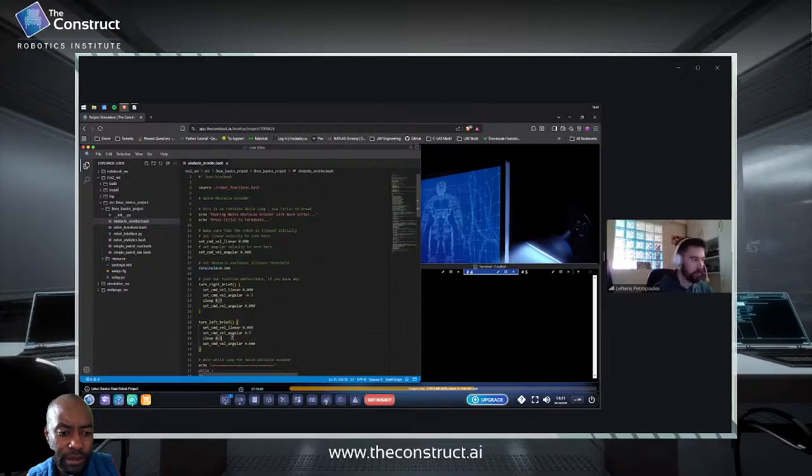Yeah, so I believe this is the part. The 0.5 here is the velocity at which the robot will turn when we tell it to turn. The 0.3, yeah, now I remember, is the amount of time for which the robot will turn at the velocity that we gave it.